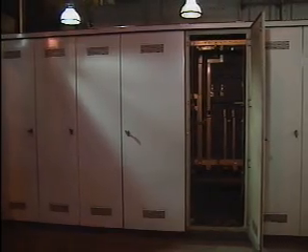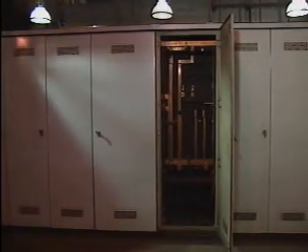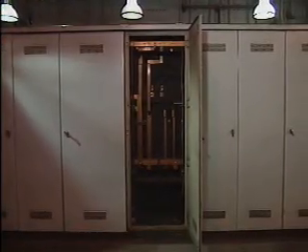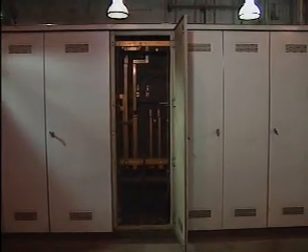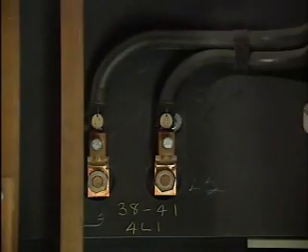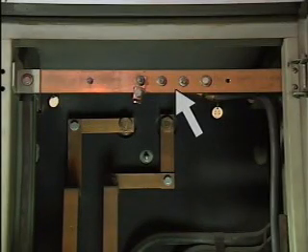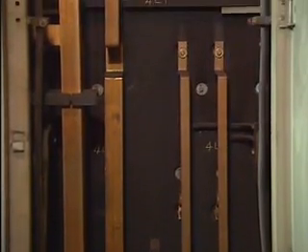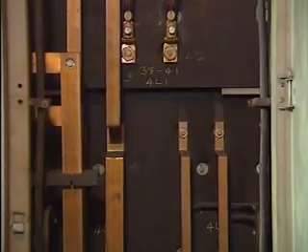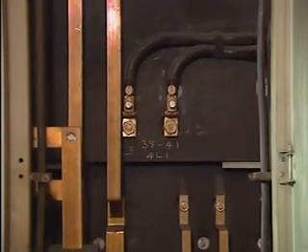For example, the equipment in this cabinet is used to provide power for plant lighting and other applications. To be able to work safely on any of these circuits, you need to know that it contains buses, connections, insulators, cables, cable supports, and a ground bus. You also need to know that during normal operation, the buses and their connections can carry large amounts of current, but the insulators, the cable insulation, the cable supports, and the ground bus do not normally carry current.